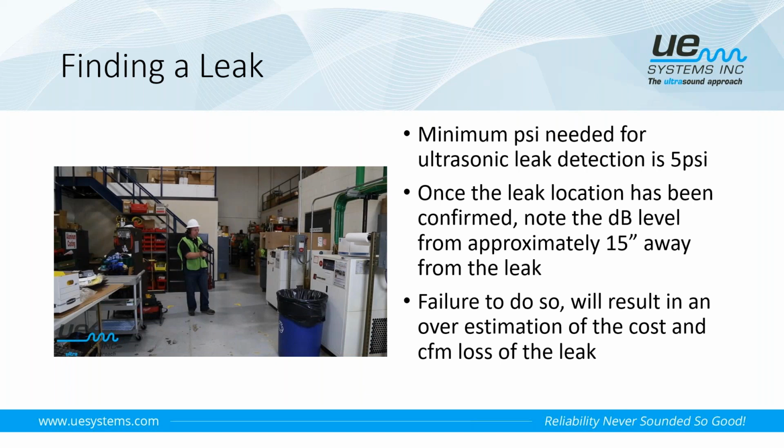When the research was done for this, going back probably 20 years ago, there's been additional research and studies between then, but the original was done probably 20 years ago. There were known leak sizes created, and then at different pressures. And what was found, as far as the distance away where we want to note the decibel level reading, that would get us as close to the actual dollar amount and CFM loss for that leak, was approximately 15 inches